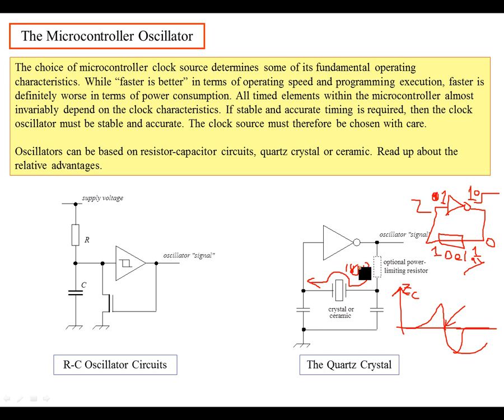Okay, so that point would actually occur in this case at a 0 degrees phase margin point, not 180. So that's the point at which this oscillator is going to be oscillating.